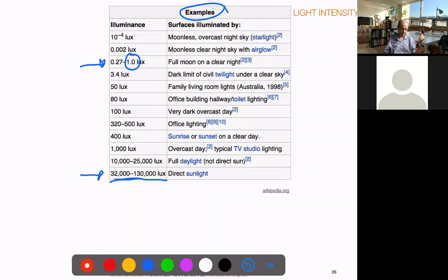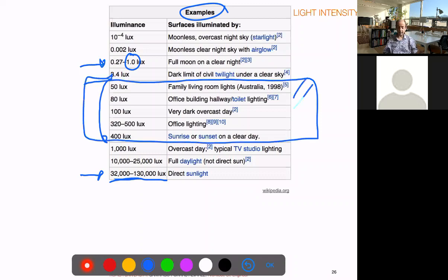But in general, in buildings for general use, we will move between 50 and 500 lux. This is more or less the range in which we move in artificial light. Of course, less for areas used just for movement and orientation, like streets, corridors, dim light. There we go between 50 and, well, nowhere they allow 1 lux, but probably in emergency lights it is between 5 and 10 lux, so you can just find your way and escape.